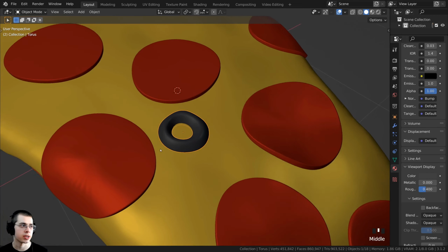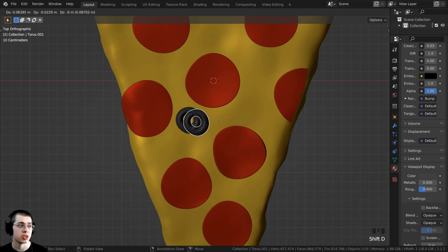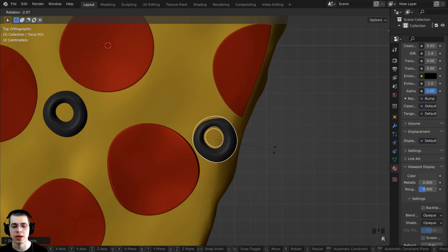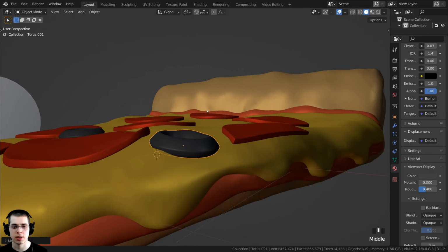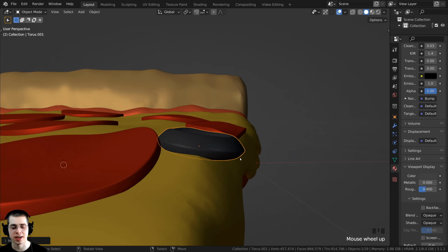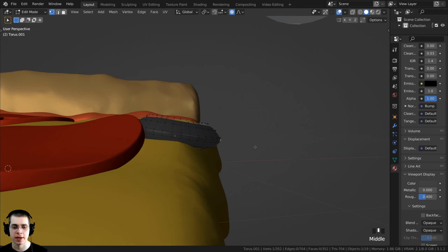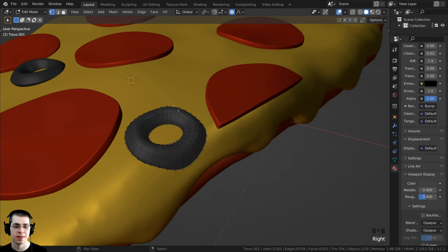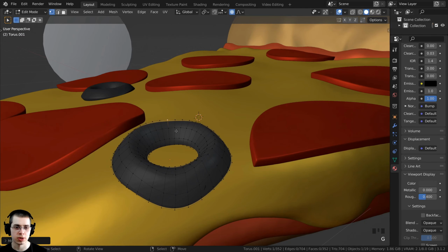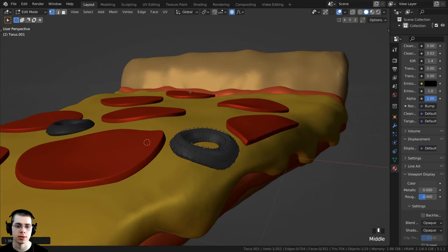All right, so go back to object mode, and then I can press 7 on the numpad for top view. So I'm now going to press Shift D to duplicate. Let's bring one over here. I can kind of give it a random rotation. And let's make this one so it's kind of sagging on the side. So I'll press Tab to go into edit mode, and then I can select a vertex here on the edge. I can press R to rotate and G to grab. And let's just bring that down a little bit so it's kind of sagging. And then just select some vertices and press G to grab and just make the shape a bit random. So something like that. All right, that is pretty good.